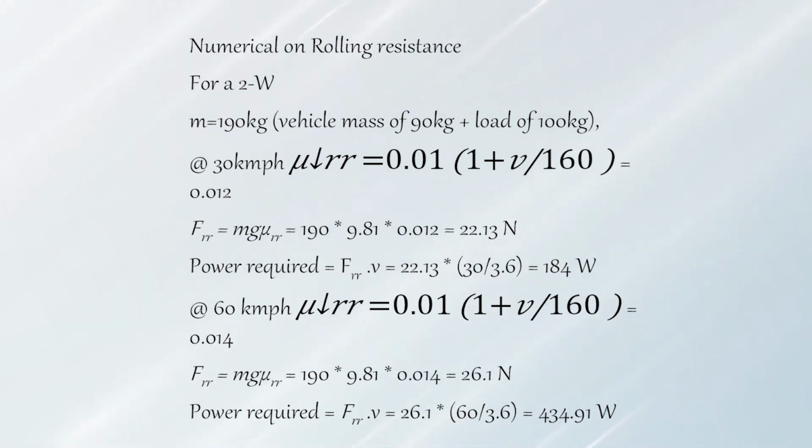Now, we have calculated the force. Now, what about the power that is required? The total power required is force into velocity, the same. So, it is 22.13 into again 30 by 3.6, which results in 184 watt.